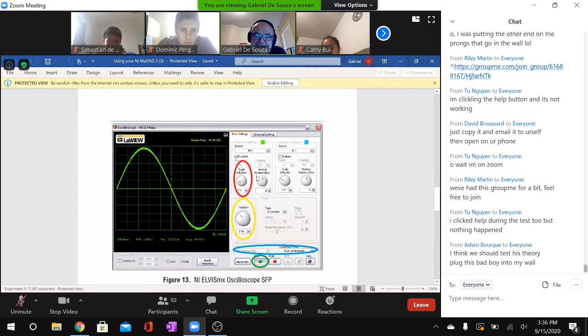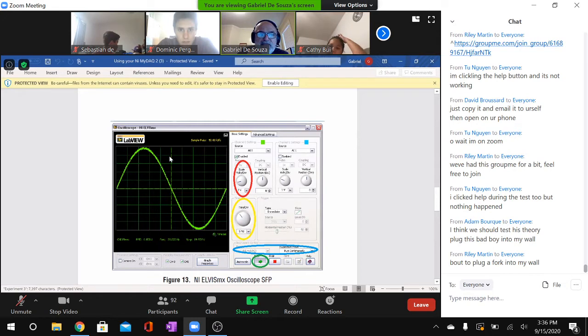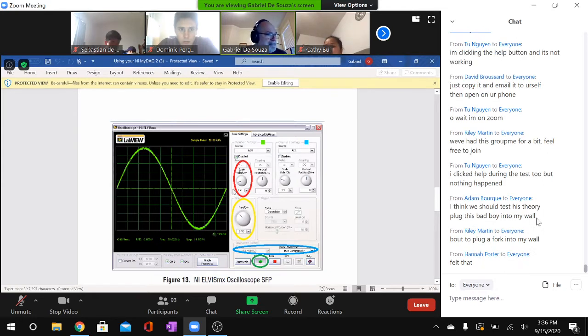That is defined here on the vertical position. So you'll be able to calculate what that is, because if you know the number of volts per division, suppose we had set this to 1 volt per division. Then I have 1 volt here, 2 volts, 3 volts, 4 volts, almost 5 volts. The one on the horizontal line is time. Time is the inverse of frequency. So F, frequency, is equal to 1 over time. Time is equal to 1 over frequency.